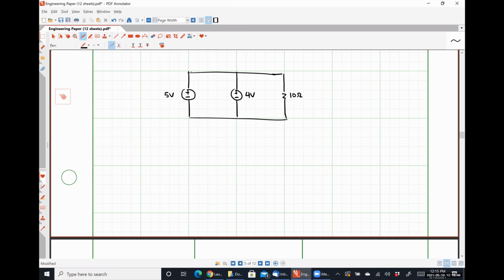My job in Bossier, where I'm designing battery energy storage systems, is literally connecting huge batteries, like 1500 volt batteries, in parallel to be able to supply megawatts of power to something downstream. But it's all preconditioned on the fact that all of the voltages are going to be approximately the same, because if they aren't, things are going to break real fast. So much so that we have battery control systems that will literally switch on and off different parts to maintain charge levels across the battery system.